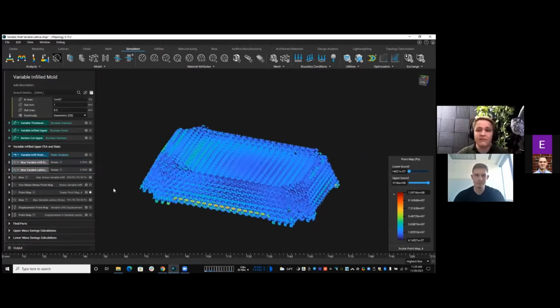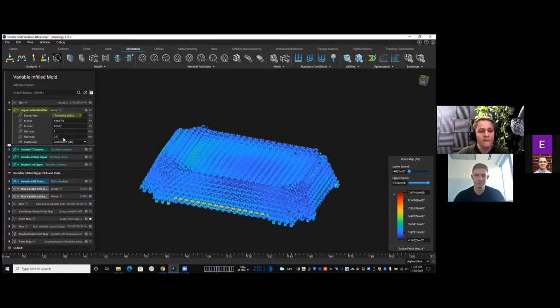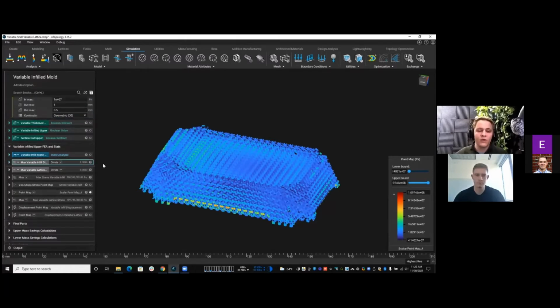It looks all nice because I have this all finished up and I'm just showing it to you, right? But from 0.5 to 1, that was not my first choice. I actually started off from 0.5 to 0.6, and then I reran and I saw, well, I still have about 11.8 thousandths displacement, right? That's not quite good enough. So I just kept increasing this number. Everything in nTop reran for me, including this FEA verification, just changed up this number until I hit 1, and I reached my goal here of below 10 thousandths of an inch of displacement.